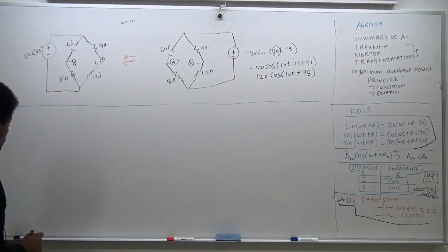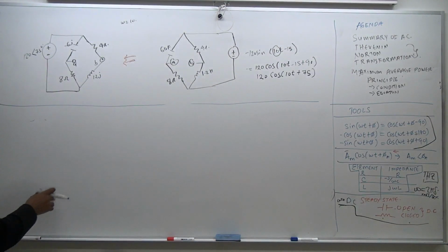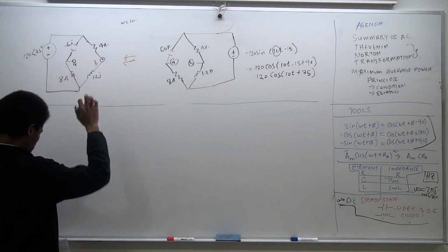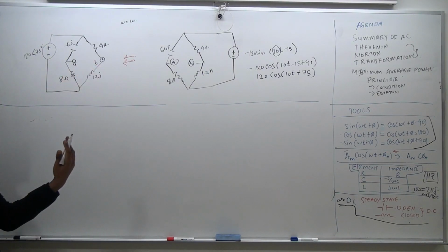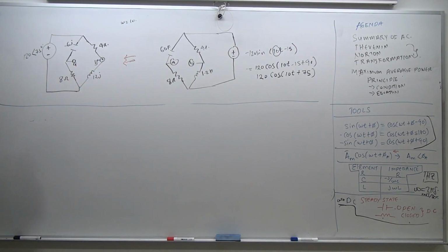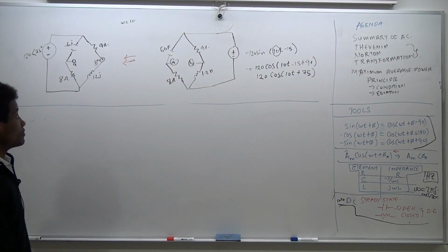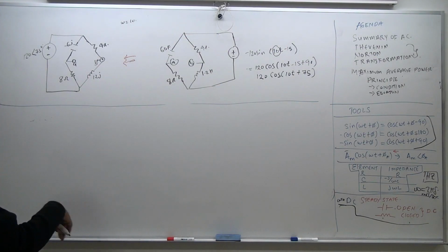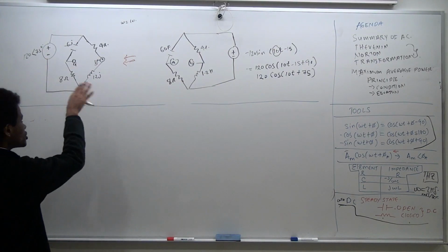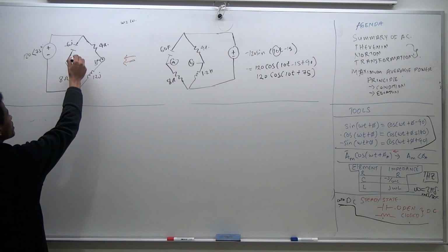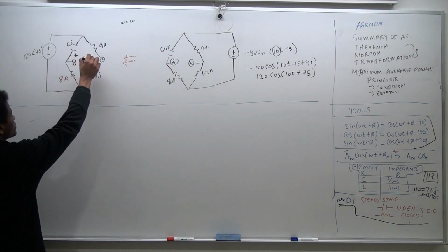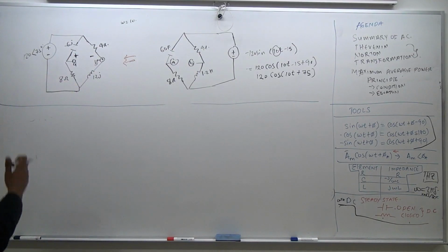Somebody is asking you to find the Thevenin equivalent of this circuit as seen from terminals A and B. When somebody gives you this kind of problem, the first question you have to ask is, what's the positive and what's the negative terminal? Because it does make a difference. Potential, even current, and all these elements can be seen as kind of like vectors, because the direction matters. I mean, the reference matters. If you told me this is A plus and this is A minus, and you change this, it's a different problem. So we're going to assume this is A plus and this is A minus. This is the first thing, and usually it's going to be provided in the problem.